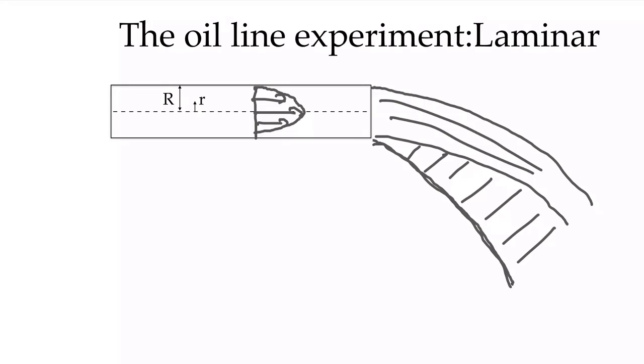so we have a lot of momentum in the center of the pipe. We have a large region with very low momentum on the outside of this pipe. When we get to the end of the pipe, that low momentum fluid has almost no inertia, and so it falls very quickly. All the low momentum fluid from the outside of this wraps around the outside of this and falls much more quickly, whereas this high momentum core fights gravity for longer and gets shot out further.